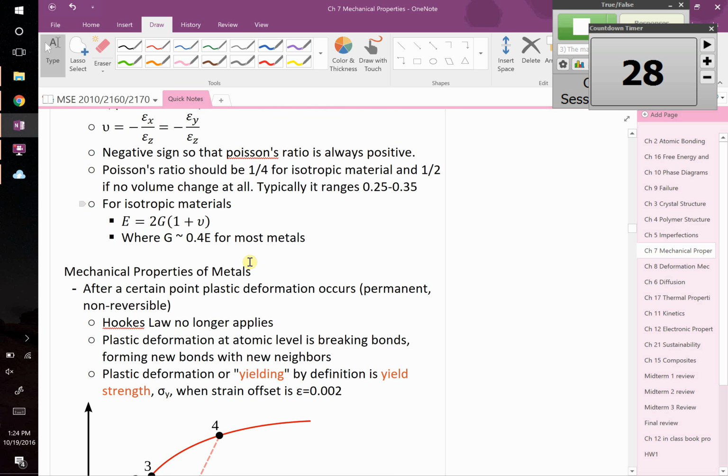If you have these values, right, if you have Young's modulus and shear modulus and Poisson's ratio, there are expressions like this one that can relate them. So this is a super common test question, homework question. I'll give you information to solve 2 of these, and then I'll ask you about something relating to the third. Right? I'll give you a plot for Poisson. Maybe I'll give you a plot for like stress versus strain. The slope of that would give you Young's modulus, right? And then I say the final dimension was this when you applied a load of that, so that allows you to figure out Poisson's ratio, because I told you how much it contracted. And then I might ask you what a shear angle might be if it was loaded under some shear stress. So you have to figure out what G is from these 2, and then solve for a shear angle.